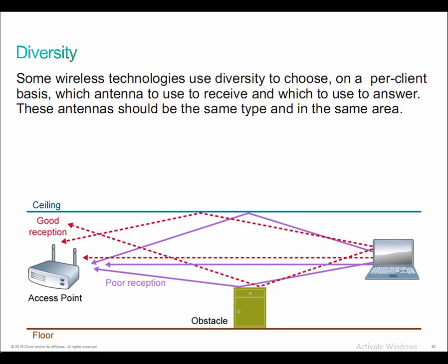Okay, we typically see space diversity in the case of wireless. Space diversity means that the signal is transmitted over several different propagation paths, and then we have multiple receivers that are spaced apart that receive those paths separately, and that's why the antennas are actually a specific distance apart. We'll talk about that in a little bit here.